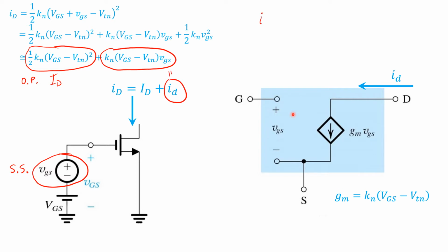So if we write out the expression that relates only the small signal components of id and vgs, we end up with this. Maybe handy to use shorthand VOV here. And here you clearly see the linear relationship. And we're going to define the constant of proportionality, lowercase gm.